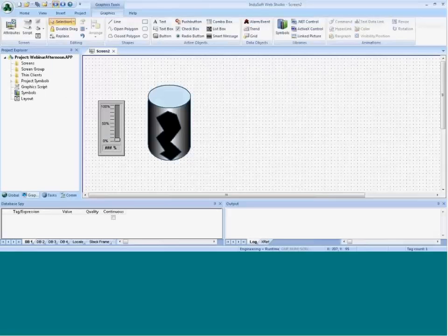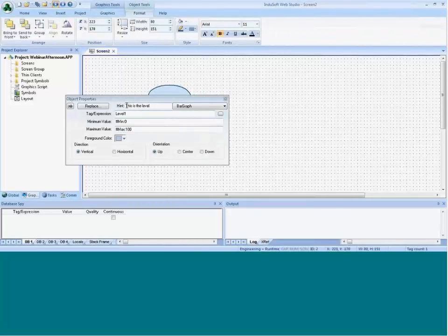So now we're going to take this a step further here, and by putting in curly brackets and an if statement, we're going to be able to enhance this a little bit. By putting in curly brackets, I could put an InduSoft function or a tag name in here, and here we're going to use the if statement, and the if will say if show hint, which is a tag name that I have not created yet. If that's true, then what we'll do is we'll show this hint text here.